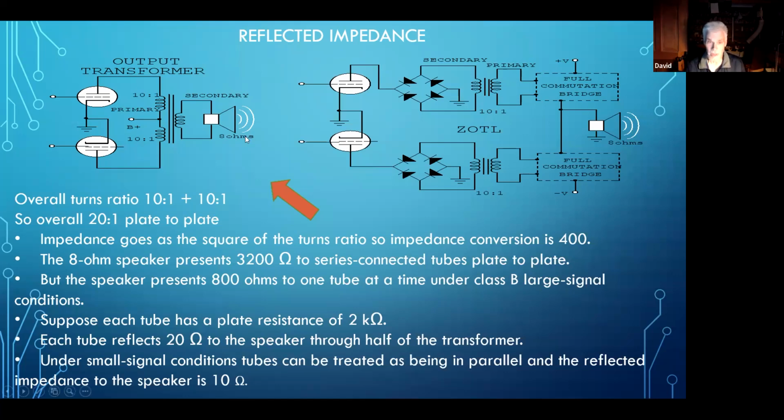So how the active amplifier devices, like the tubes, respond to that matters, because the tubes have transfer characteristics. They respond to what's coming back through the transformer, and they behave in various ways depending on whether they're tubes or transistors, or whether other feedback is applied that affects it. It gets kind of crazy.